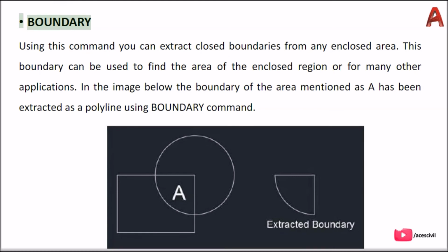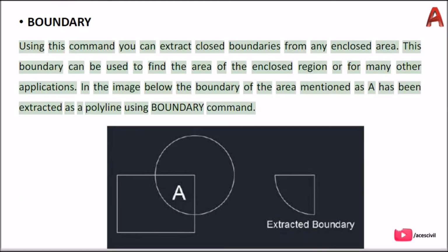Boundary. Using this command you can extract closed boundaries from any enclosed area. This boundary can be used to find the area of the enclosed region or for many other applications. In the image below, the boundary of the area mentioned as A has been extracted as a polyline using the boundary command.